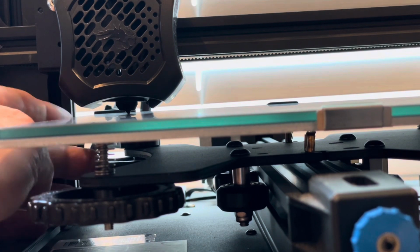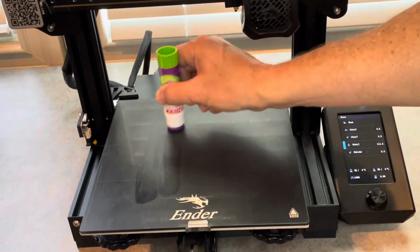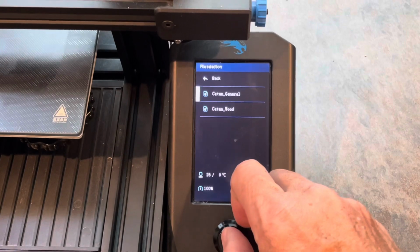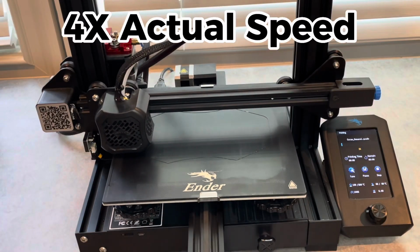This next step is not mandatory, but I suggest applying a layer of glue from a glue stick to the bed to stop the print from separating from the bed before it's done. Now you're ready to print. Select your file and click Print. Be patient because even the smallest 3D print can take an hour or two.